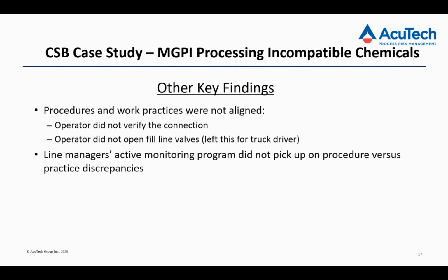There were problems between practices and procedures. Like I mentioned earlier, the operator was supposed to verify the hookup and open the valve. And on this day, he just left after pointing out the hookup. In fact, CSB found some confusion even among the operators about what the proper practices should be.